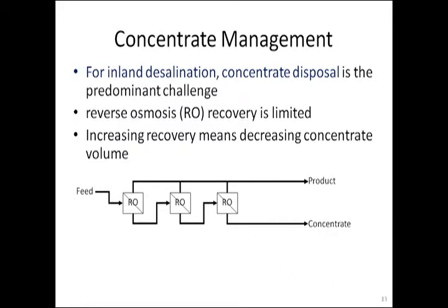So in the work that we've done, we're particularly looking at inland desalination, where concentrate disposal, to me, is the predominant challenge. In seawater desalination, as Ralph pointed out a few talks ago, you can put the brine back into the sea, and as long as you are careful about how you do it, there doesn't seem to be any significant effects. But in inland desalination, concentrate disposal is expensive. It has potential ecological issues associated with it, and so to me, it's the primary challenge that we face.